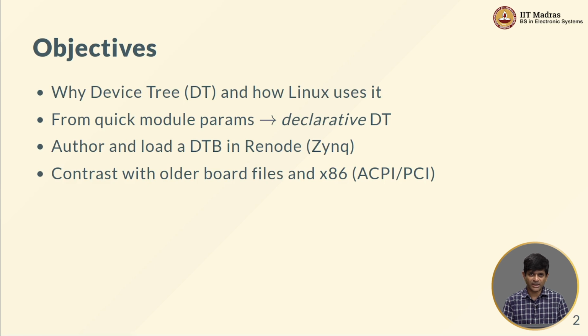And after doing all of this, which is pretty much the way that we currently use in order to implement the loading of drivers for devices, I am actually going to take a step back and say, is this the only way that it could have been done? Well, the answer obviously is no, but in the past the approach that was followed was actually different. There was an approach using what are called custom board files, and not just that, on x86 PCs, your desktop, laptop, any Intel or AMD based system, there is a completely different approach which does not use the device tree, but uses something else called the ACPI configuration interface, right.